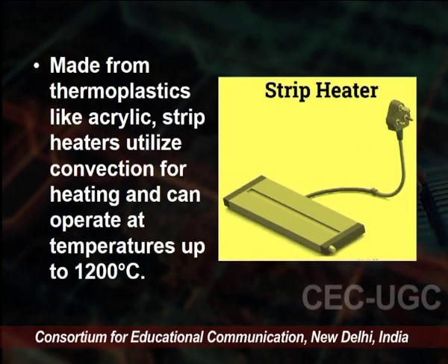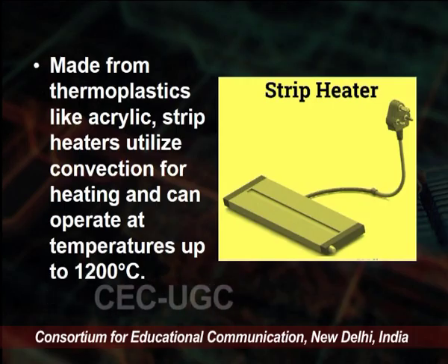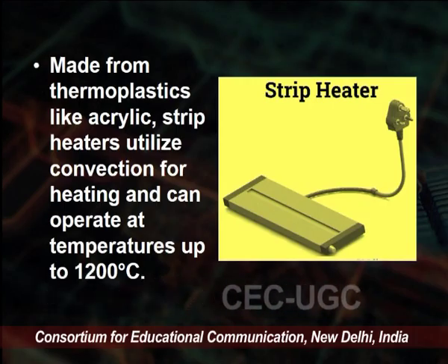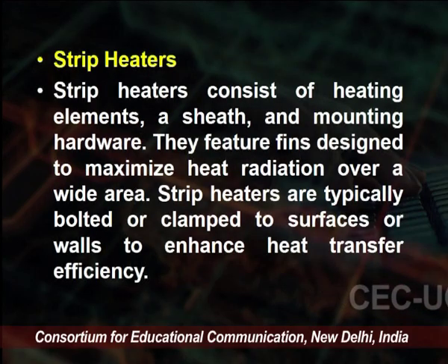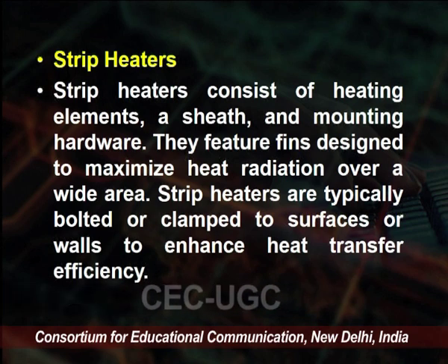Next is a strip heater that we have already discussed, and this is the strip heater. This strip heater consists of the heating element mounted in hardware, and they feature fins designed to maximize heat radiation over a wide range. Strip heaters are typically bolted or clamped to the surface or walls to enhance heat transfer efficiency.